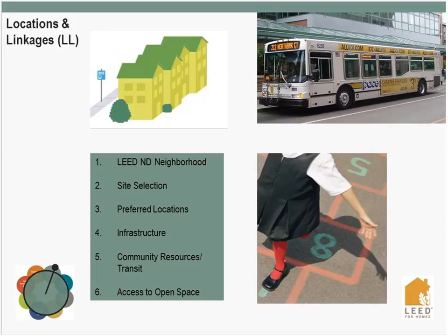So, really a lot of times with your project, you get some points or you don't, right? I mean, you don't really get to pick where your project is, but if you do get to pick, and if you also get to, at the city level, make some recommendations on what could be around the area, especially if you're doing LEED and ND certification, you can pick up a ton of points. This is where you can grab some points. In this version, there are no requirements for location and linkages as far as how many points you need. So those are just some extra things that you might be able to pick up or might be able to consider if you're trying to place a building or consider where your client wants to build.